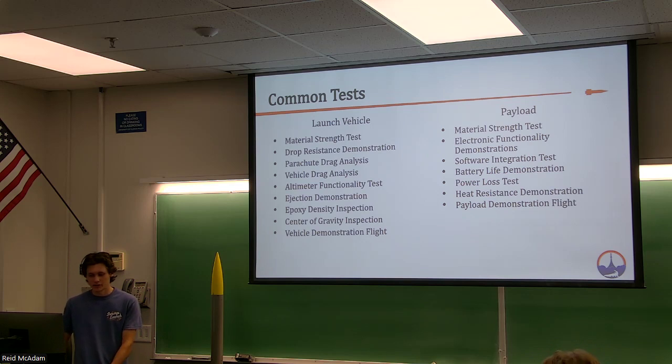And you got drop resistance demonstration. You could do it under parachute. You could do it off of a smaller surface. So that could even be an in-flight test pretty much. You could fly a rocket and have it land and be undamaged and say, okay, that proves that when we go to competition in April or June, our parachute is going to slow things down enough that it won't break on competition day.